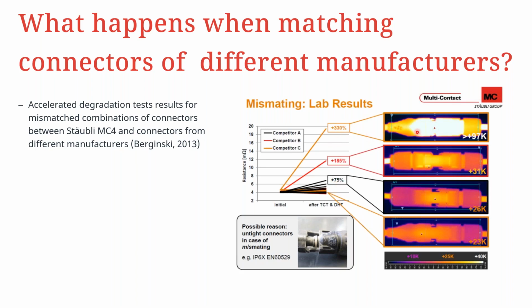So here what we are saying is that when you have to use MC4 plugs, please make sure that you are using MC4 plugs from the same manufacturer, because for on-roof or even field installations, the use of MC4 plugs is almost a must. So it's not recommended that you start joining wires the normal way you make wire joints. Therefore, for PV installation, even to offer you security when you have to isolate some modules, MC4 plugs are a must, but please only make use of MC4 plugs from the same manufacturer, and make sure that they are securely connected to each other to minimize the risk of arcing.